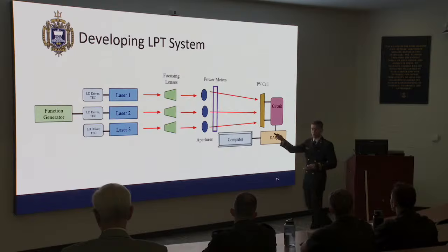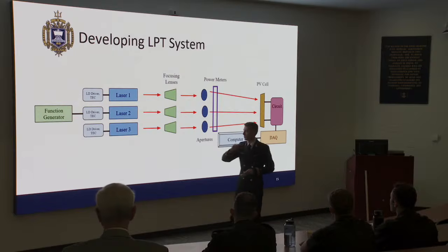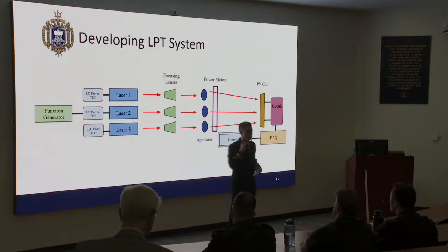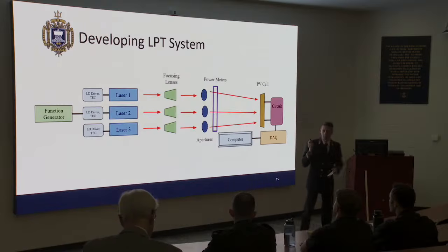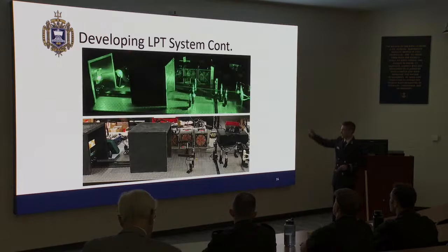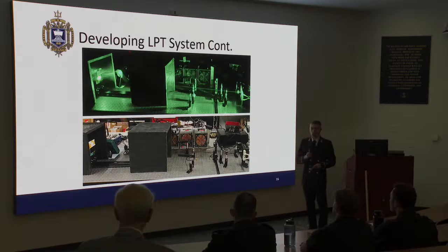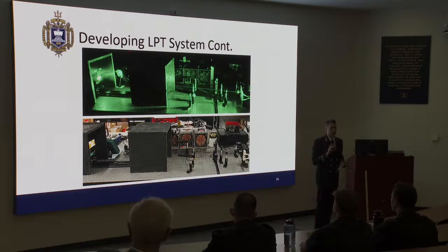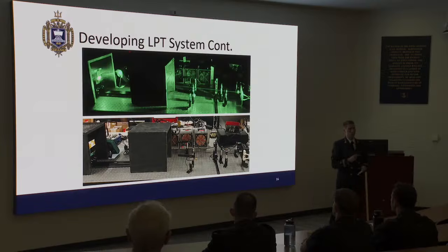We also used a function generator, similar to the LED experiment, to externally modulate the lasers to introduce that communication scheme. This is what the structure looks like in actuality. You can see the top with it powered on and the lights off. Unfortunately, only one of the 3 laser diodes operates in the visible spectrum, so although all 3 of them are currently lasing, you can only see the 520 nanometer laser.